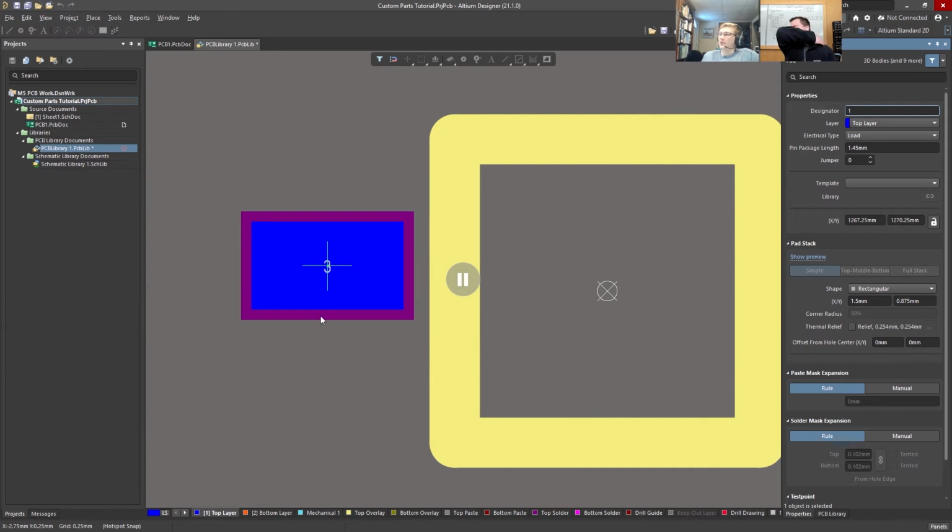That purple edge actually defines the solder mask. They're going to put the solder mask on your board, that's the green color or whatever color you choose. And that prevents you from putting solder everywhere. It covers the things that you don't want to solder to, and it leaves exposed the pads. The way that they put that solder mask on usually is a photolithography process, and that mask can move a little bit.